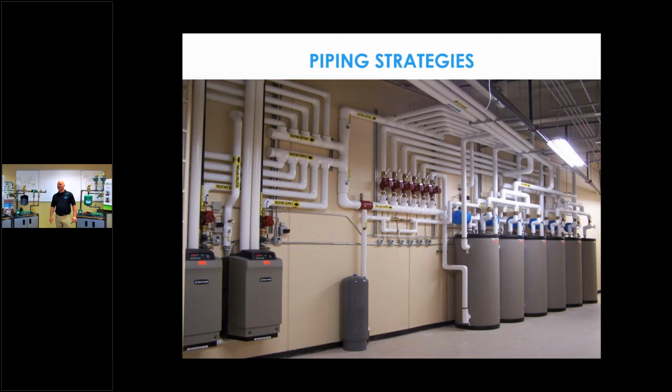Yes, everybody's saying yes. Okay, it's primary, secondary. It's a multiple boiler application. Is it piped properly? Is it reverse return? I will put the highlighter on here and you answer, Jim. This is the supply coming out. It goes here, first in. Here's the return. It comes up, over, and here it's the last out. Does that pipe properly? Getting a lot of yeses. Yes, it is. Great. Okay.